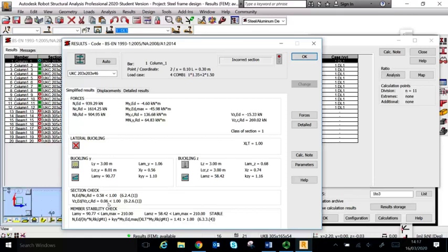So it is satisfactory in axial sense and shear, but in stability for buckling, using the formula for buckling calculation, the factor for buckling is 1.41, which is greater than 1, and that means that the section failed, it is an incorrect section. So this section will have to be changed.